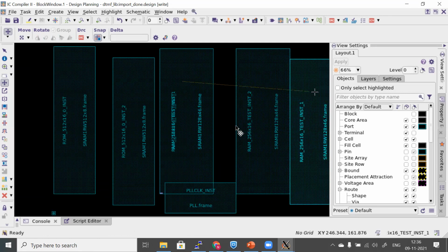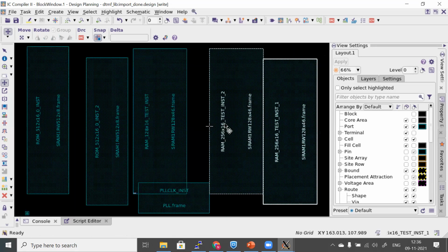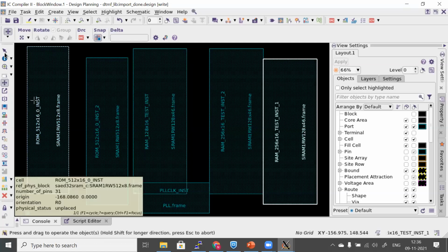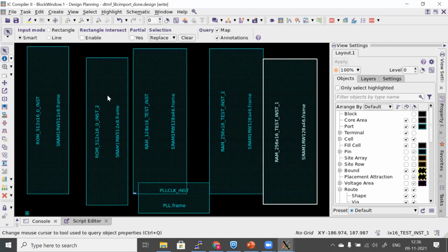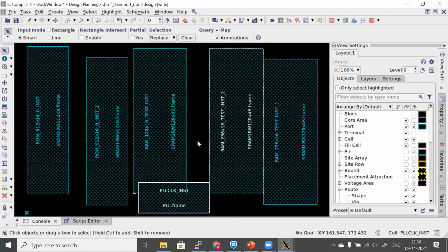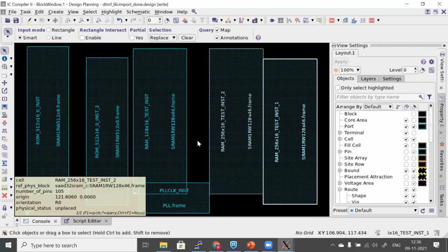So if you want to fit the page, use F. Are you able to do that? And escape. It will come out of that selecting mode. So if you want to select, you need to use this arrow mark. Then only you can select in this tool. Like this. Use M to move this. Anybody has any doubts? Please let me know. Done? Oh, I think the time is up. Okay. No problem. Just give me 2 more minutes.